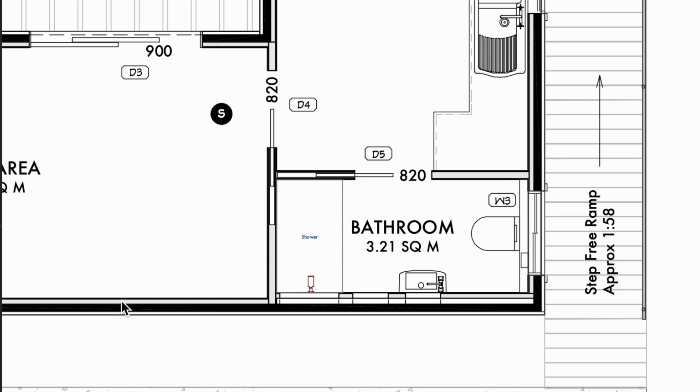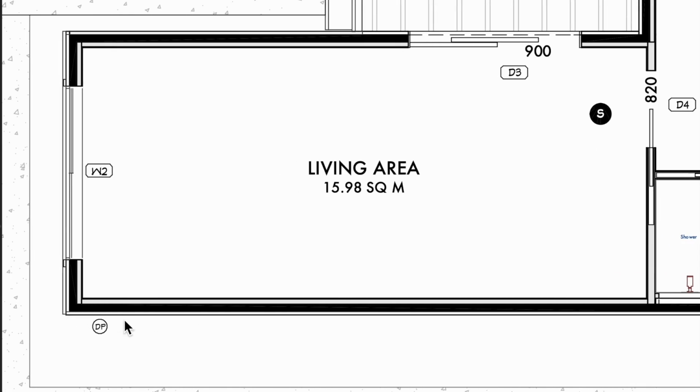I might as well give it the same lengths and just specify what those materials are. For me, it's going to be an interior frame at the Studco 51 by 35 studs, and then I've got all this material in between, which is going to make my offset, and then I've got battens that run horizontally along the wall, and then the Colorbond cladding goes on top of that. You don't have to do that. You just put 0 for these if you're just doing a straight frame for your exterior, this black line here. Forget about the offsets. But it does help if you want to calculate the same thing all at once with some sort of accuracy, instead of doing a separate calculation.